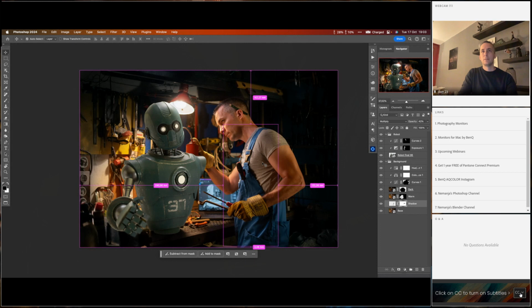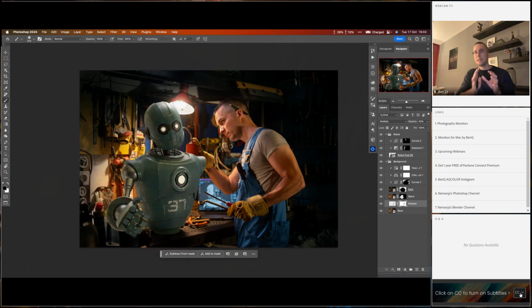and move it maybe right there. Maybe, I don't know. This is just an option. So with these small tweakings, with these fake shadows and fake things, you can fool the viewer's eyes that there is a shadow from the robot. It's really soft shadow because there is a big light here, but yeah. And also this light is washing that shadow and this light, and you'll have something soft. You can make it a little bit harder, but also lower the opacity, and it will be enough. This is before, this is after, just a little bit of that trick.